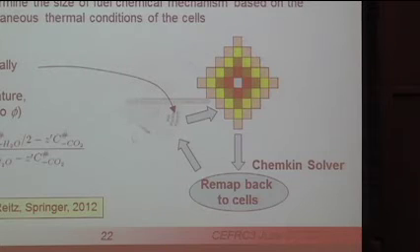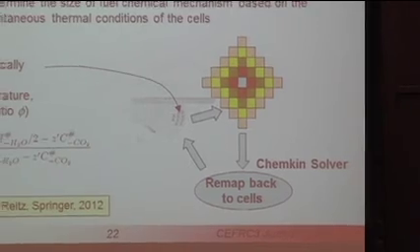The other approach that also saves significant computer time, especially for very large mechanisms, is to dynamically determine the mechanism size based on local and instantaneous thermal conditions. So for example, when you're late in the combustion process, and most of those ketones and the intermediate species are no longer present because they've all been consumed, why carry them in your mechanism? Get rid of them. And therefore, you can reduce the size of the mechanism from 3,000 species down to 1,000 or whatever it is. So significant savings is possible. And that's described in Long Liang's paper.